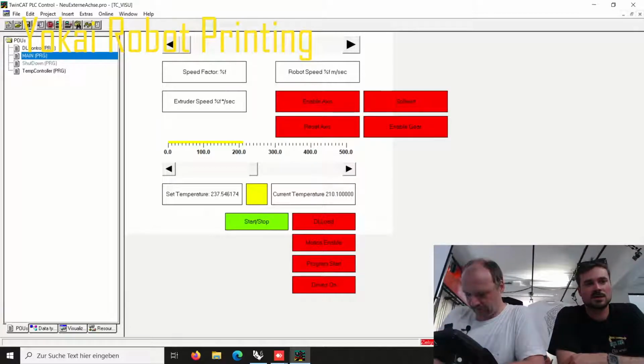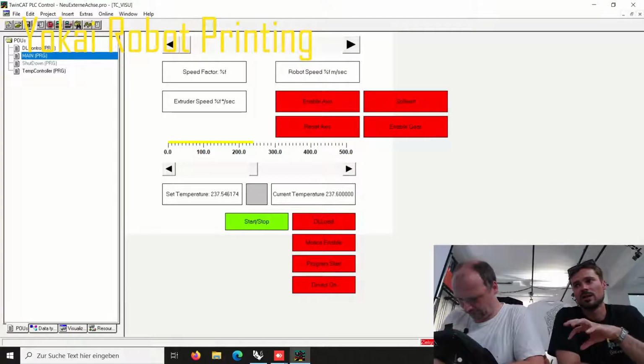It is going to be extruded at 240 degrees Celsius temperature, so it's getting melted and will be extruded in a liquid state, and in this state it will get printed on the shirt so that the liquid filament is already running into the fibers and will stick on the garment.